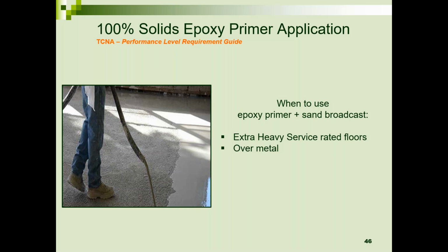If you're working with an epoxy moisture mitigation membrane, oftentimes the recommendation is to use a sand broadcast into that epoxy membrane to enhance bond, mechanical bond, of whatever you're throwing on top of that. An epoxy primer is often used with underlayments or topping products that are rated for surface traffic, to receive heavy traffic without a flooring material over it. Also, an epoxy primer might be useful if you're working over an elevated access floor, a metal access floor. Epoxy works great, but a sand broadcast might be recommended to enhance bond of the products to follow. So as I've been preaching, always read the tech data sheets from your favorite manufacturer, what they recommend over non-absorbent surfaces, over metal, if that's the case.